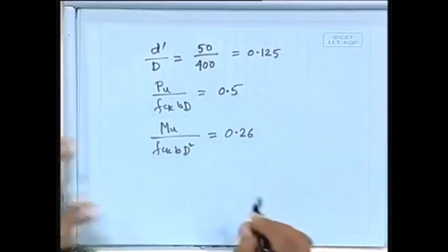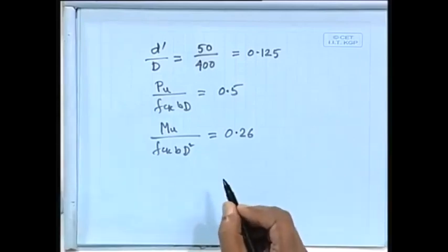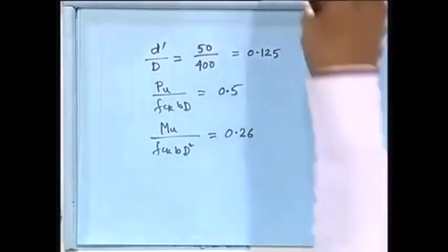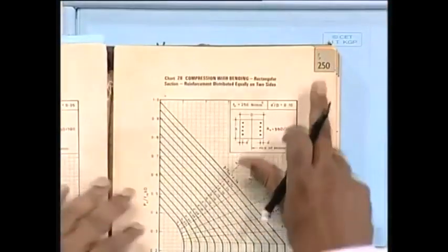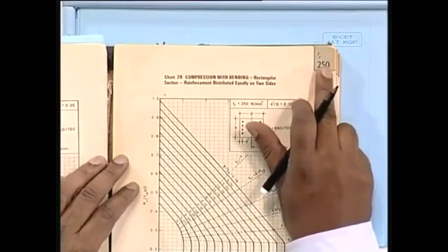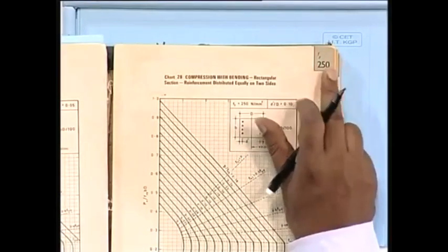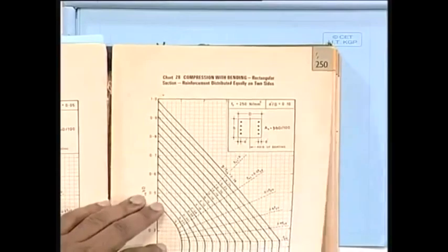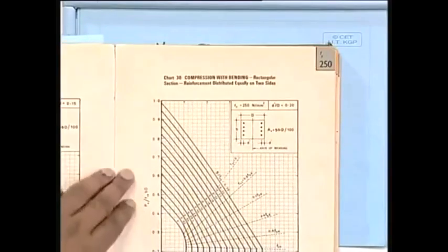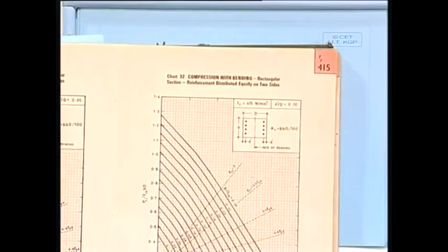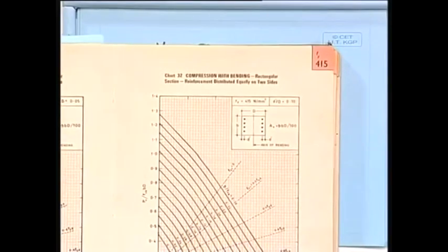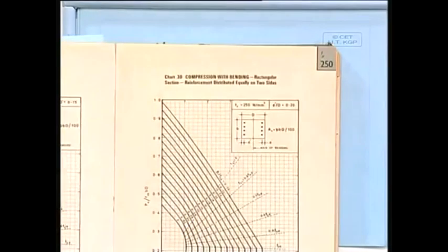So we have to find out the area of steel, and from this special publication, we are having so many. If you see this side, actually it is written that steel grade, here it is Fe415. Okay, just only to mention this one, let me tell you. So we can get it here from chart 31. Please note down chart 31.